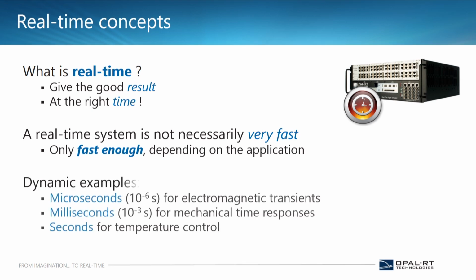For example, if we want to send voltage and current signals from our power system network in a virtual environment to an actual relay at t equal to 20 seconds, that means the relay should accept the voltage and current signals at t equal to 20 seconds so that it will be able to operate. The hardware devices are always synchronized to a physical clock. The physical clock is nothing but your wall clock or a wristwatch. So the real-time simulator is synchronized to that particular wall clock. When we are running our simulated MATLAB model on a real-time platform, the results that we obtain from the simulated platform will be synchronized to that physical clock.